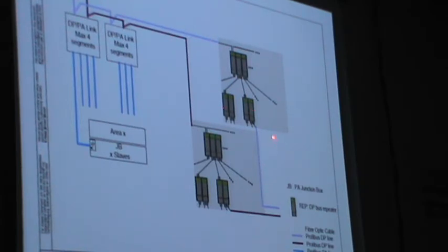And here is how we configured it. From the DCS you also have the repeaters like this, because when you transmit the signals to the field, again we are giving repeaters in the DCS also. On the panel side and in the JB in the field, there also we use repeaters. So both ends have repeaters, and there will not be any speed variation in the signals. You will get the signals immediately, and the communication will be normal. Otherwise the communication will get disturbed.